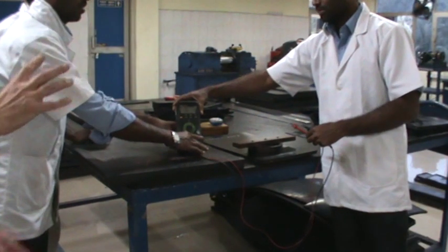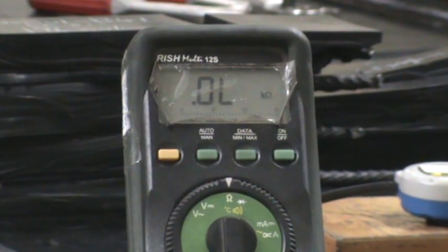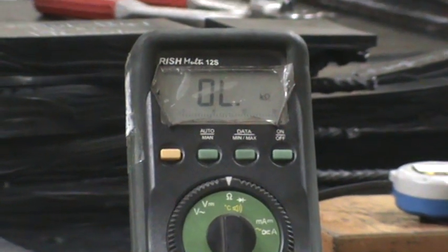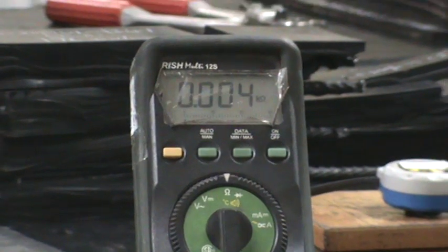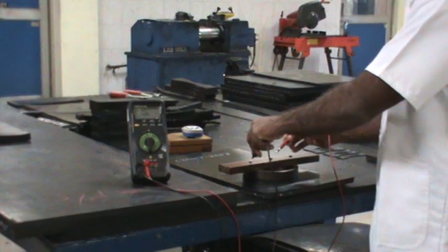C. Electrical resistance. The electrical resistance of a conveyor belt is measured in ohms or megaohms. This is a measure of how much the rubber will resist electrical current. Low resistance means the rubber is a good conductor and therefore will not allow charge or sparks to develop, making it suitable for underground mining.